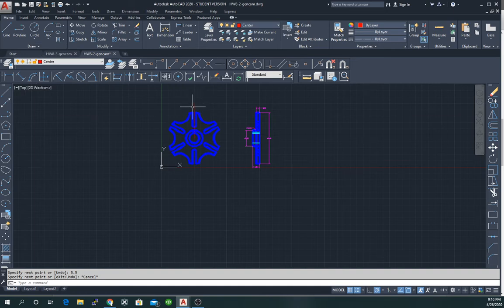Now, we could, if we wanted to, make a radial array. I haven't done this, but let's see how that's going to work out. If we went to polar array, specify the center point of the array. Okay, so I selected first. Typically, you would choose array first, and then it would say select objects.